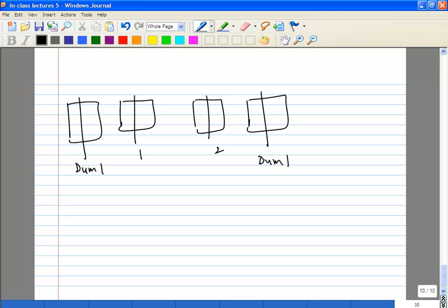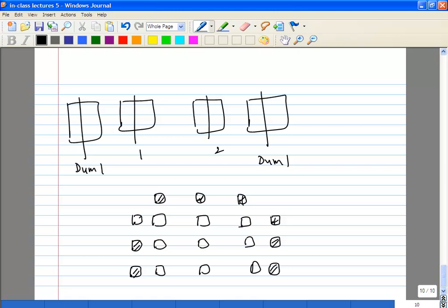And in reality, you want to have dummies in all directions. In this case I have shown a very simple array. So let's say you have something like this. So your transistor is laid out in 9 sections. You probably want to have dummies in all directions actually. You want to have something like this such that it's protected on all sides, and ideally these dummies will be identical to your main transistor section. So every transistor in all directions will see the same number of devices and the same environment.